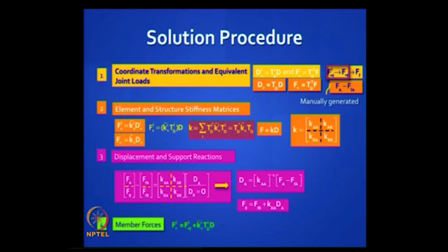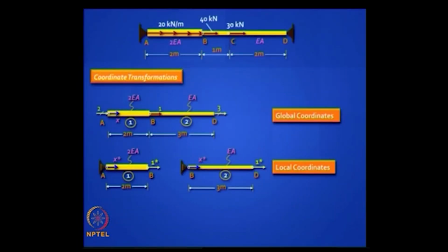Remember, when you are using reduced stiffness method, use a different notation for your element stiffness matrix, K tilde, that little curly thing on top of K, that is how you distinguish. And again, remember, if you have distributed axial loading, that is the part that you have to manually superpose. So I want you to see this one problem and you will get to understand how it works.